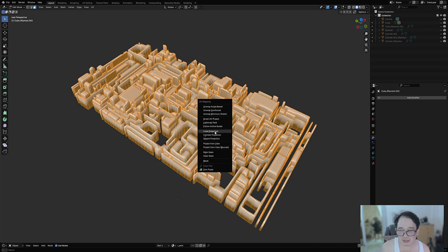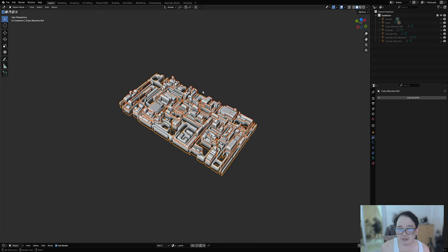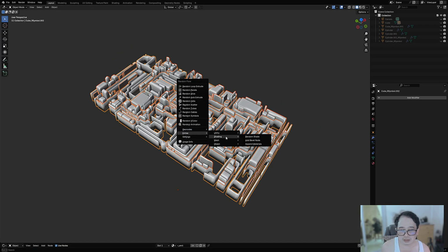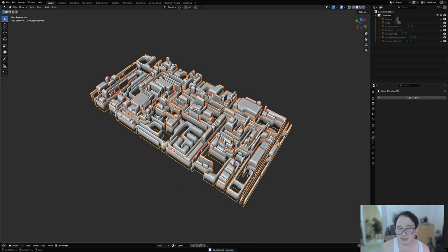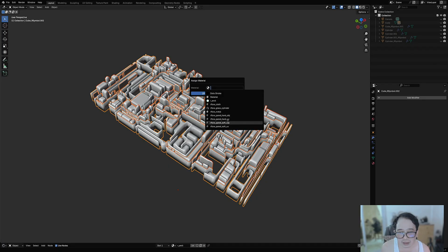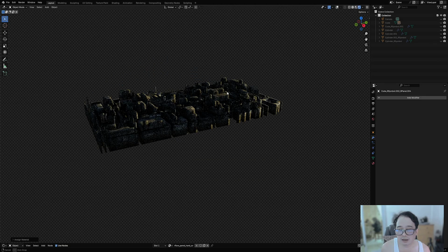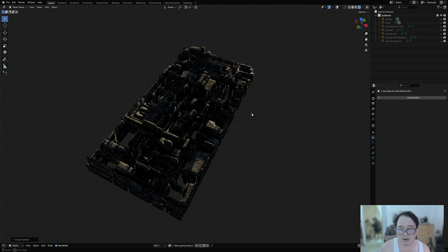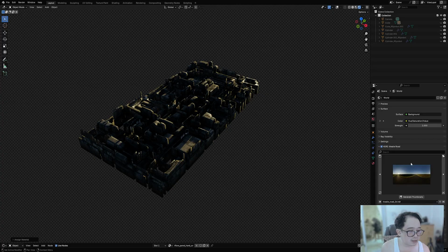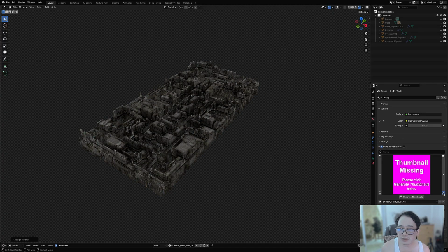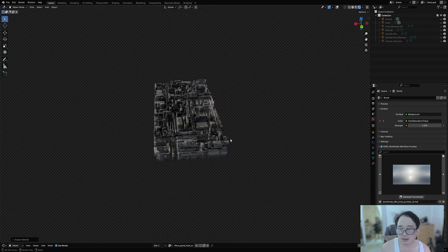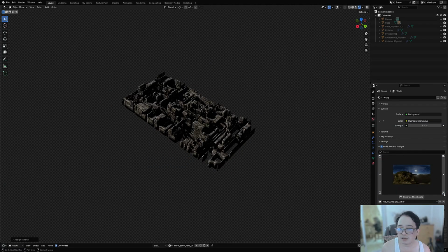Okay, let's use cube projection, then extras shading, open materials, and then we're going to go to materials, assign material, and our full panel soft, hard UV. So trying to render to actually trick our viewer that this is a bunch of buildings in a certain distance. Okay, let's try and use this.